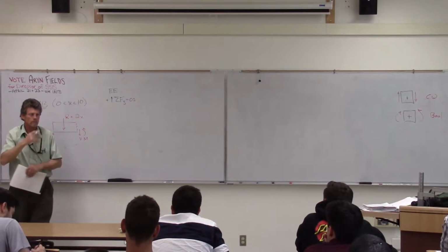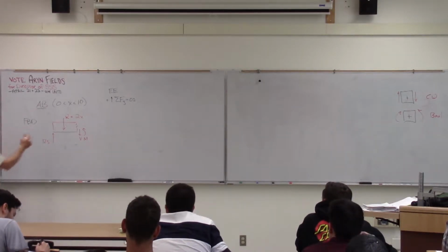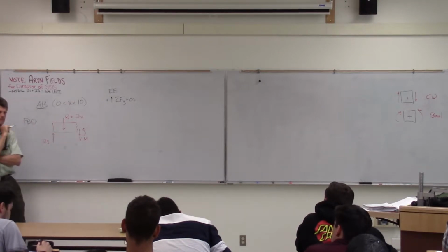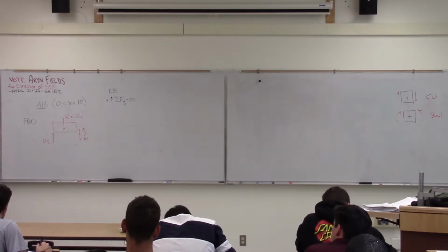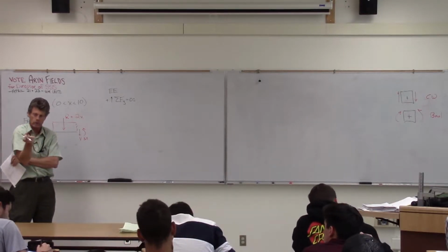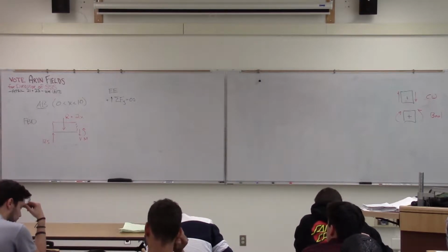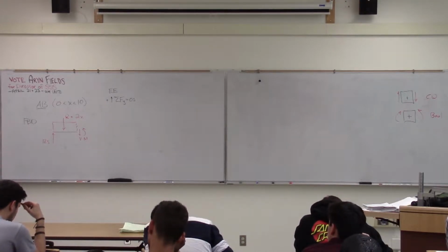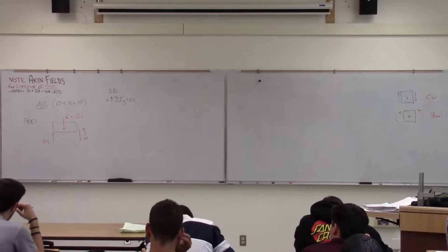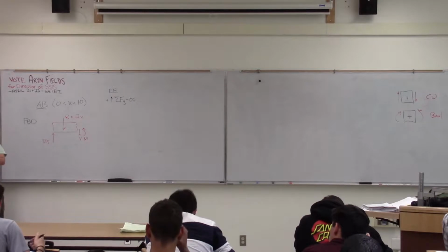Isn't there the concentrated force too? At 10? Well, but notice I'm just short of 10. So that's a good point. That's a very good point. These equations are not valid under a concentrated load or a concentrated twist. So we have to be a little careful. What we're going to do is go right up to that point, and then we're going to jump across it and make a cut there. And we'll see what happens. But good point. So there's no concentrated load at this point.